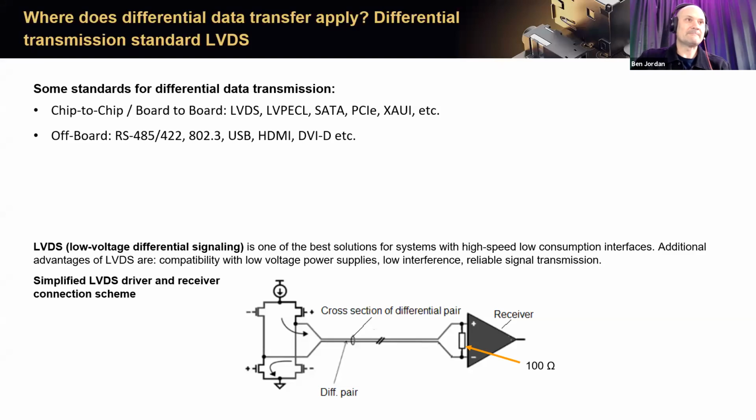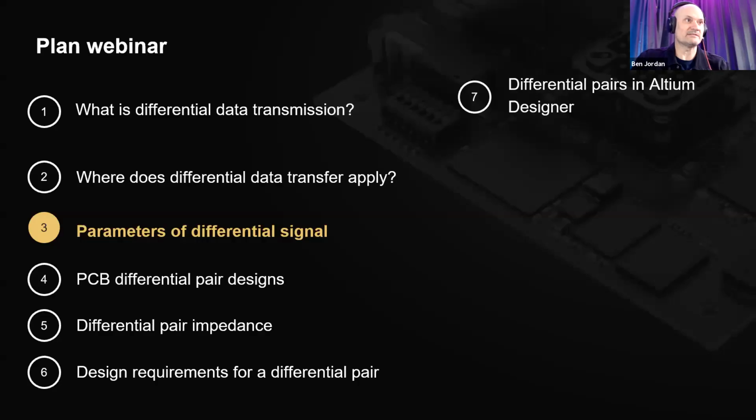It's not like the old analog microphone for a PA system where you have a long balanced line cable and you may disconnect the ground in some situations, or disconnect it at least at one end to stop a ground loop hum. It's not like that where you have transformer galvanic isolation, because all of this is referenced both at the receiving end and at the transmission end to the ground on the circuit board. You still have to have good ground planes and good grounding practices on your PCB design.